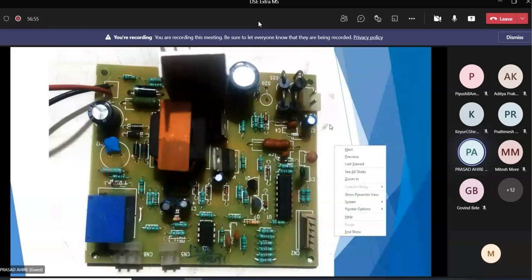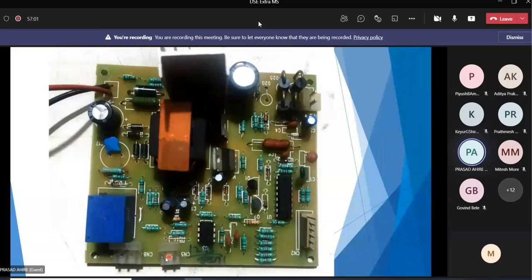So I will explain the working. First of all, we have to connect these two terminals and these two terminals with the help of connectors, a short circuit, then the circuit will be complete. Then we connect the transformer to this 3 pin connector. When the input comes, the step down transformer steps down the voltage. This is the relay to protect the circuit from any damage. After the transformer, the supply is given to this relay, and after the relay to these four diodes.